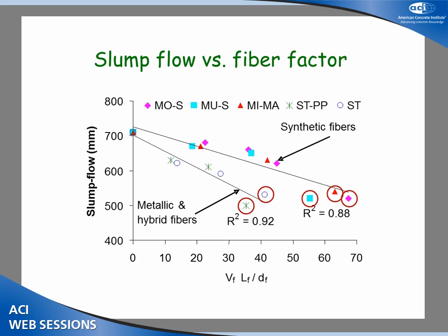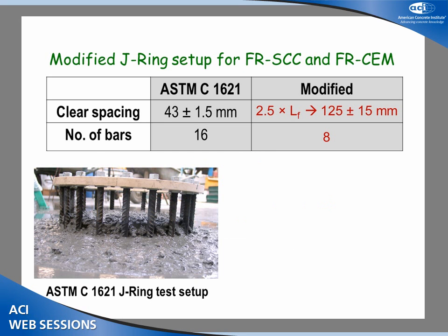And you see that these are the synthetic fibers, which are flexible fibers that can flow much more easily versus the rigid fibers, the steel fibers. In some cases we get into the 20-inch. We started at, I think, 29 inches, and you get 20 inches, and that's definitely not SCC. It's at best a super workable concrete.